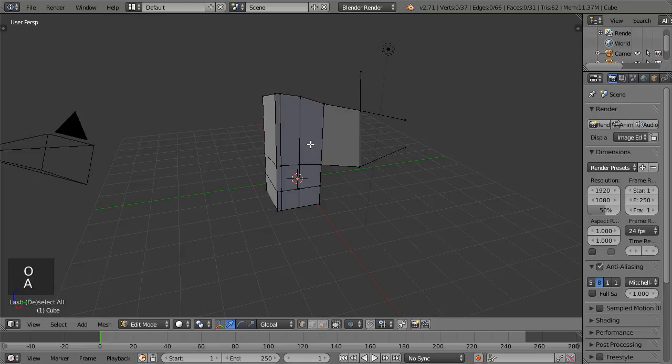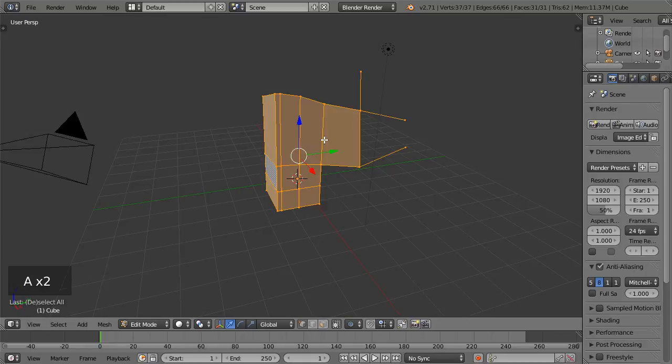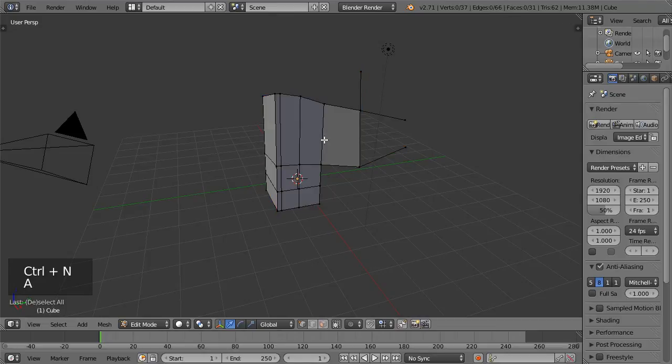And right now I'm going to select my mesh and hit Control N. So Control N is recalculate normals. If you ever have a problem where there's mesh bits facing the wrong way, it'll recalculate the mesh based off of where its brother and sister normals are.